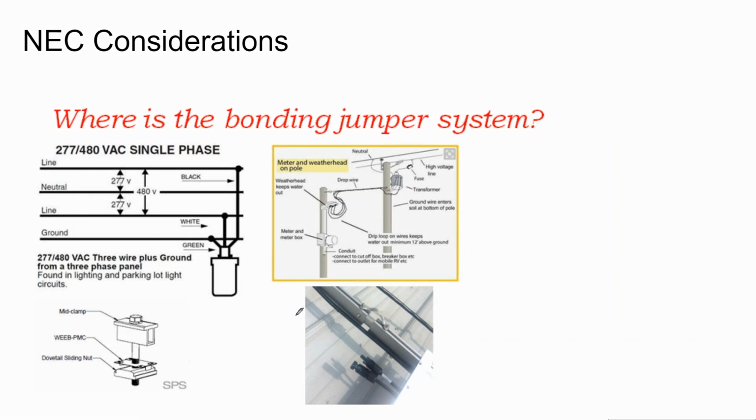And so typically you're going to have a ground rod at the side of your house, and then often the utilities will have another ground rod that's grounding at the pole. And so the good rule of thumb for your off-grid homes is just to remember to get 2 ground rods and put them in right next to each other.